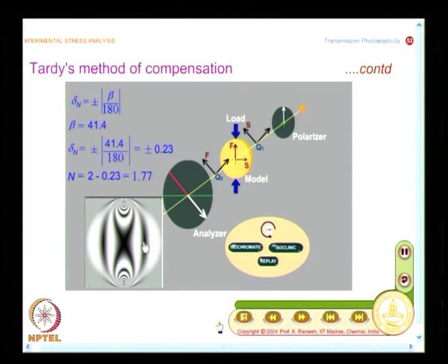So, what I find here is I have been able to get a fringe order passing through the point of interest. We will see this animation quite a few times, and you should also look at what the shape is when it passes through the point of interest. I am moving the cursor. What is its shape? It is like a figure of 8.